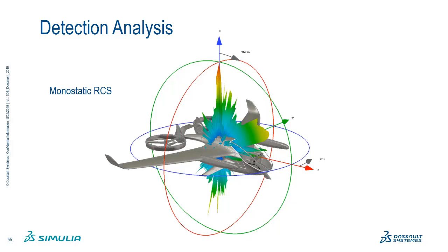Here we see the profile for a small air taxi aircraft. The scattering is relatively small from the front and sides, much larger from above and below. It may be necessary to design in scatterers to ensure that the aircraft is sufficiently detectable. This will of course need to be harmonized with other requirements, such as aerodynamics.